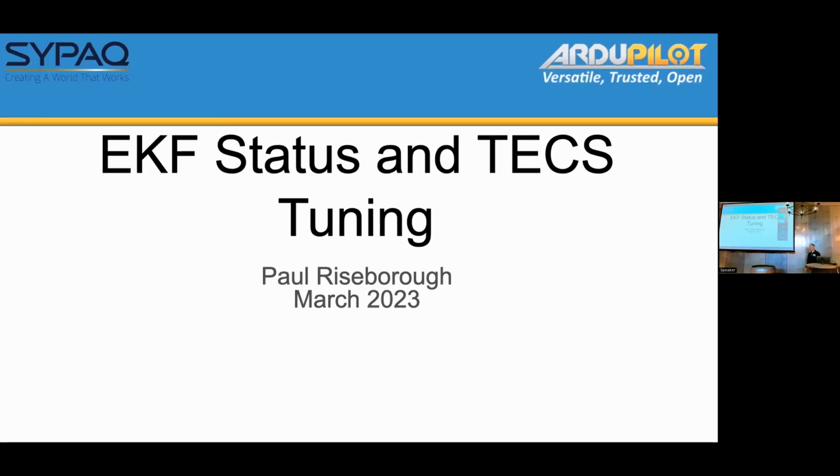Anyway, as I was saying, TECS has turned 10 this year, but the other impetus for providing a tuning update is that since the last conference, we've updated the TECS control loops. And what that's done is it's done two things. It's improved the control over the flare maneuver so that we no longer run with an open loop sink rate demand when we reach the flare.